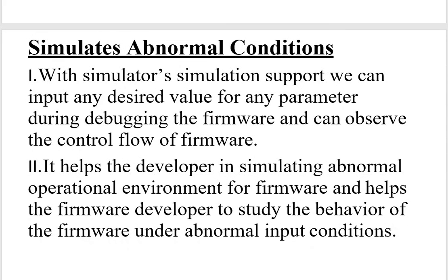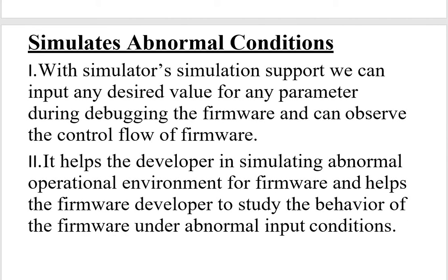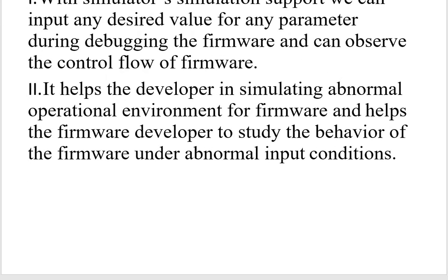And the simulation can also simulate abnormal conditions. With the simulator's support, we can input any desired value for any parameter while debugging the firmware and can observe the control flow of the firmware. It helps the developer in simulating an abnormal operational environment for the firmware and helps the firmware developer to study the behavior of the firmware under abnormal input conditions.